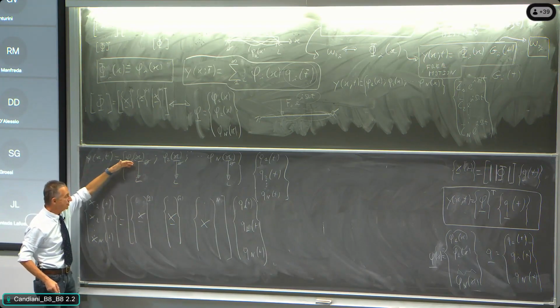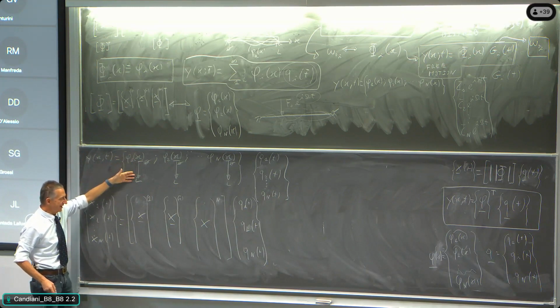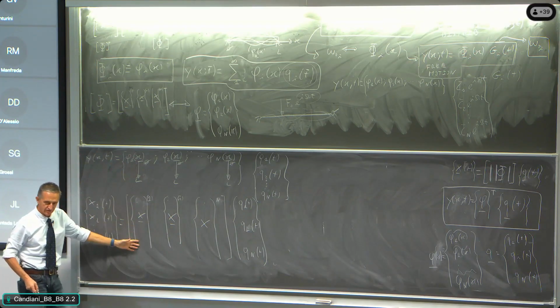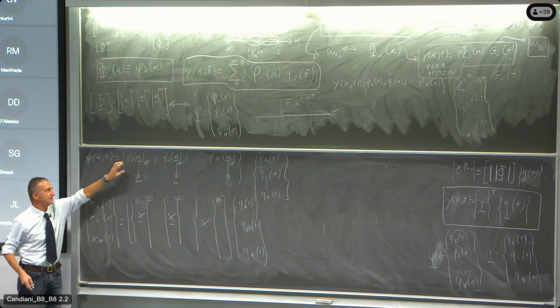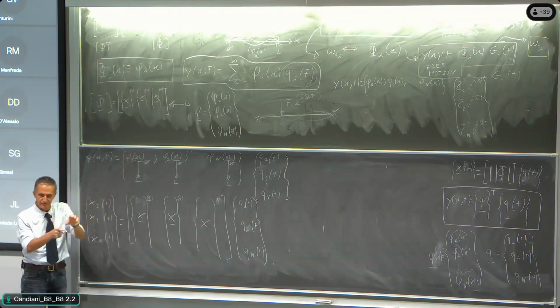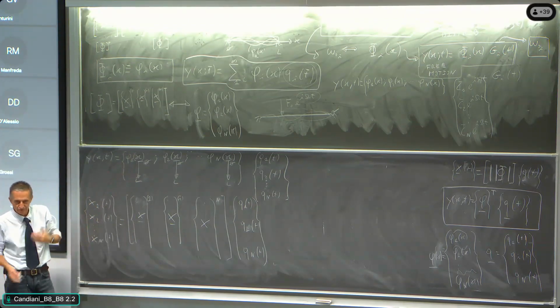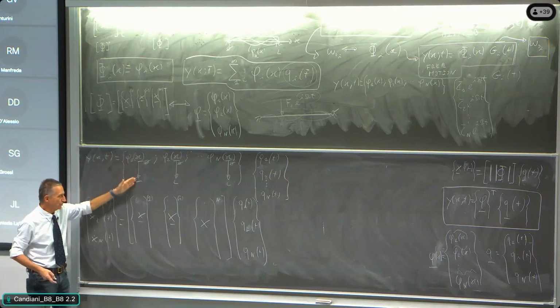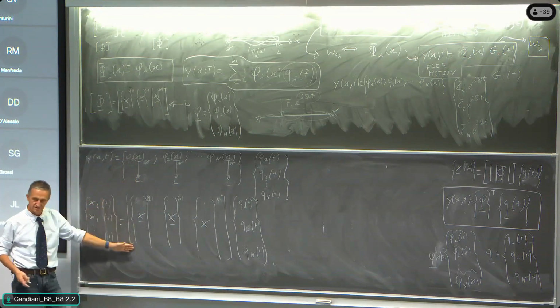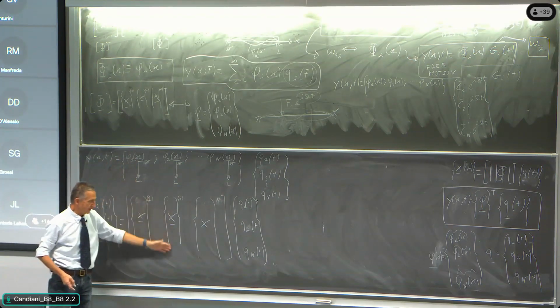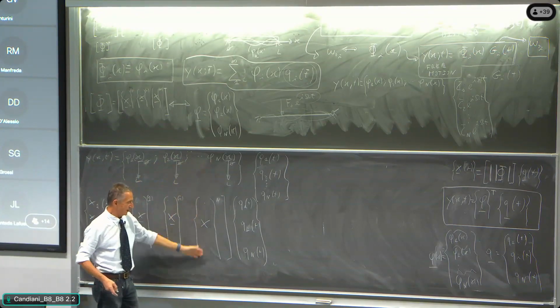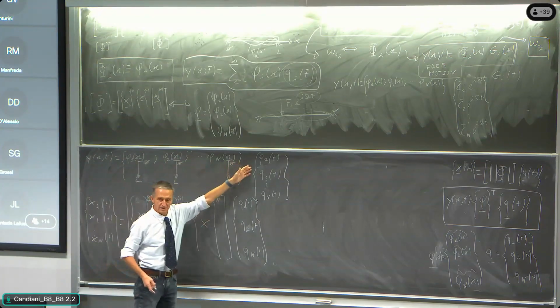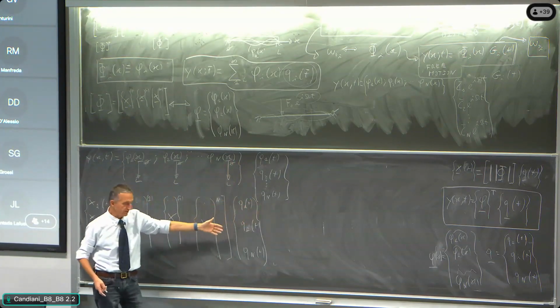And you are reading that here there is the equivalent of the eigenvector that is into the n degree of freedom, but just represented very simply as phi function of x, finished. But of course, we have the drawing here that is exactly this one. And then the second eigenvector, that is the second eigenfunction, the nth eigenvector, that is the nth eigenfunction, and finally there is the vector of the principal coordinate that is exactly the same.